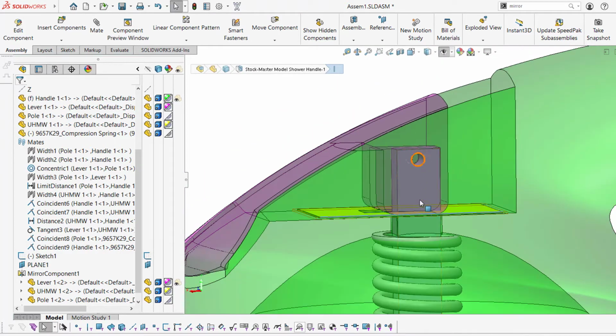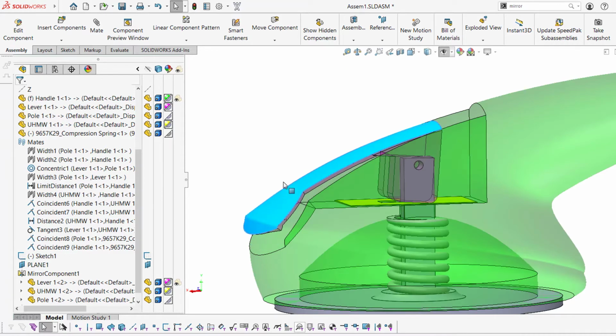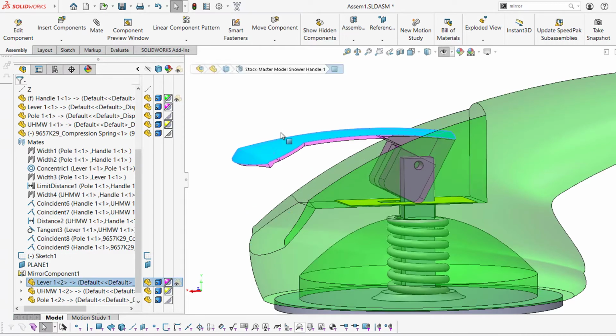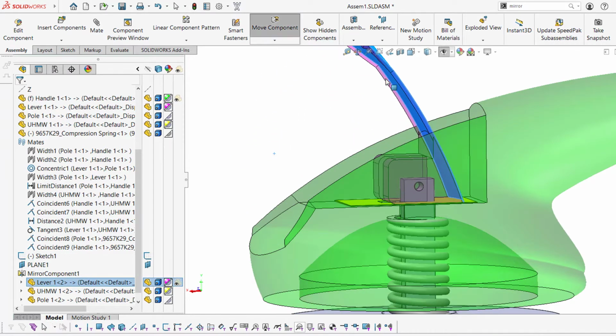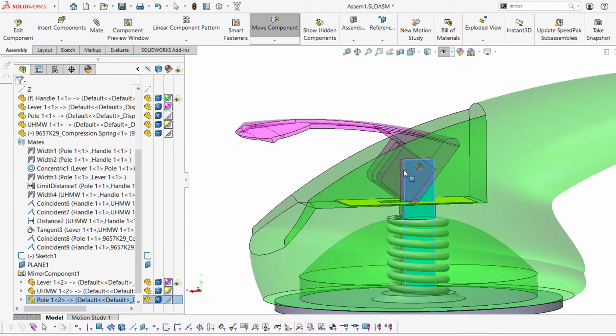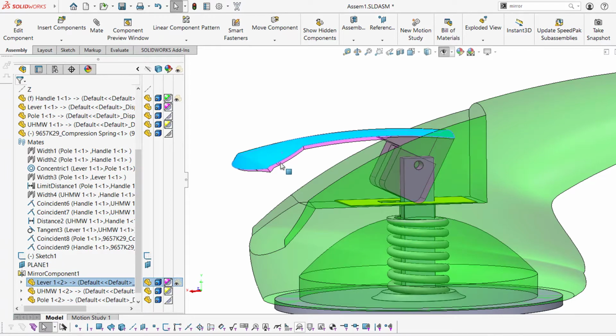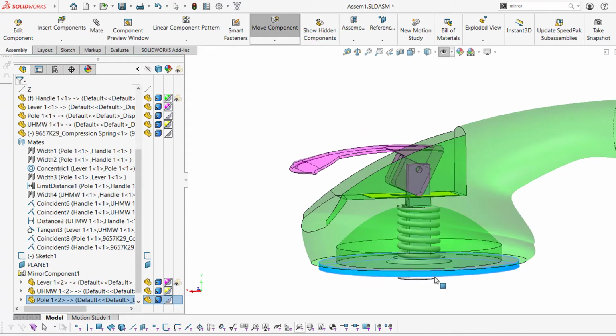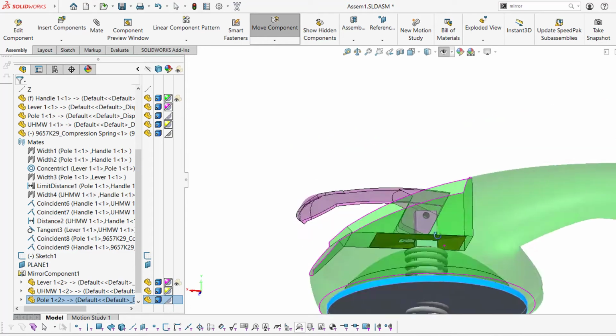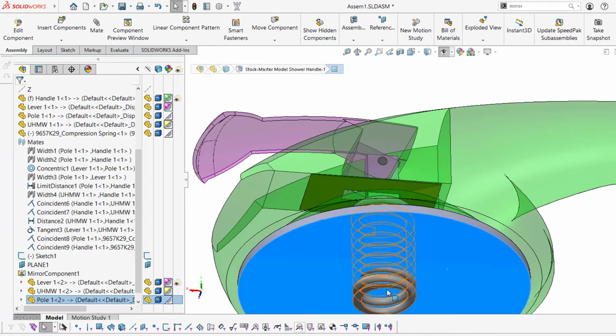When the handle is engaged right now, the distance from the center of the circle to this bottom face is larger than the distance when it is disengaged, right over here. So you basically want to move the rod up by actuating the handle, because when you move the rod up, we want to move the suction cup up because it's going to create a vacuum here.